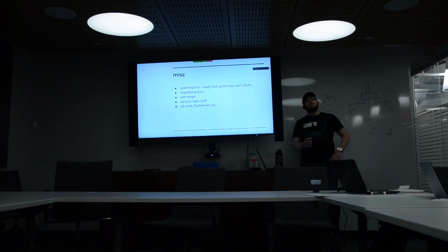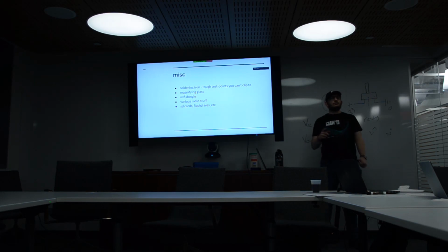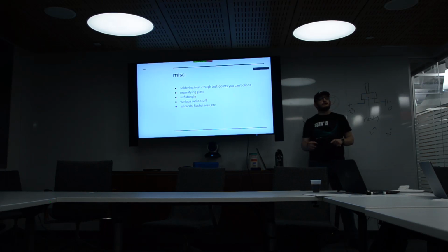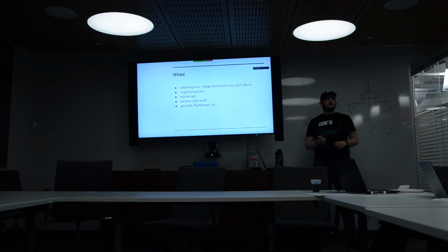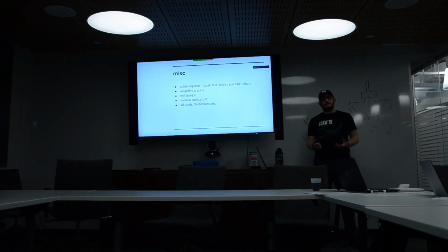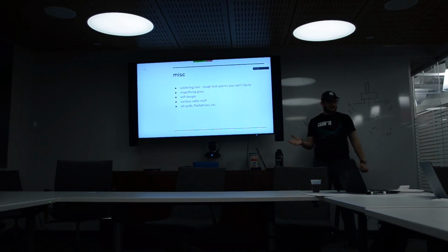GNU Radio's major issue is that I don't really know of good packages that output it to other tools. So for getting an understanding of what actual bits are going over the air, it's fine. It's just going to be a little bit cumbersome to get that into a tool that can actually understand different protocols. Whereas if you buy a dedicated Zigbee dongle, for example, there's the KillerBee suite that just works with it.